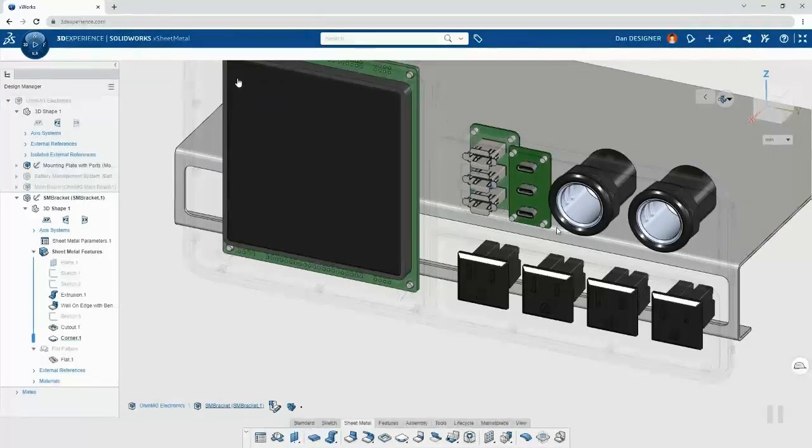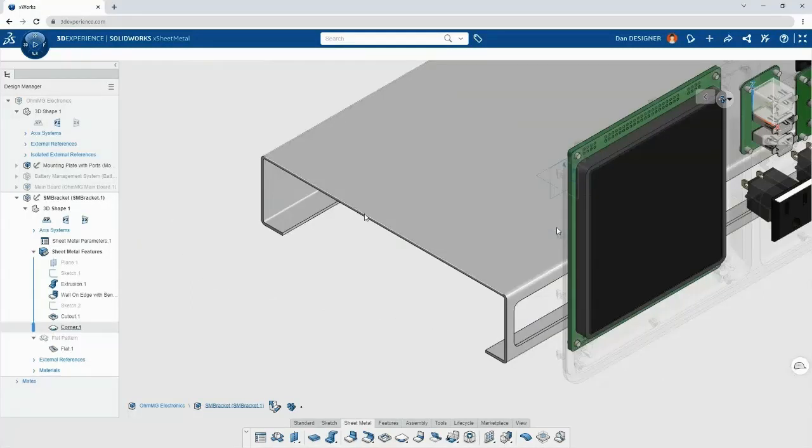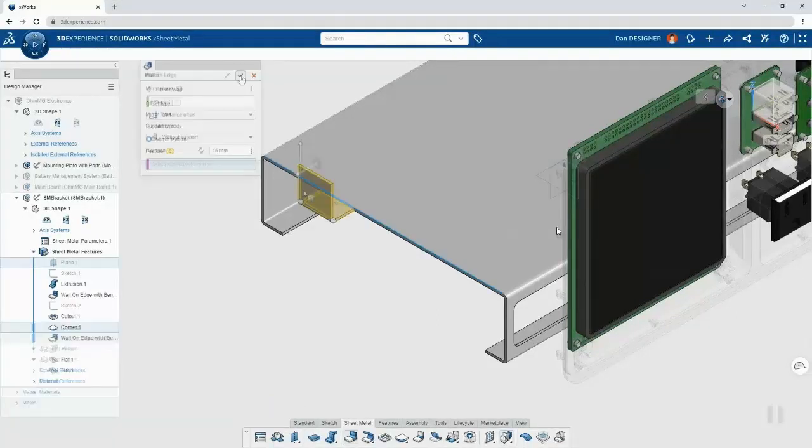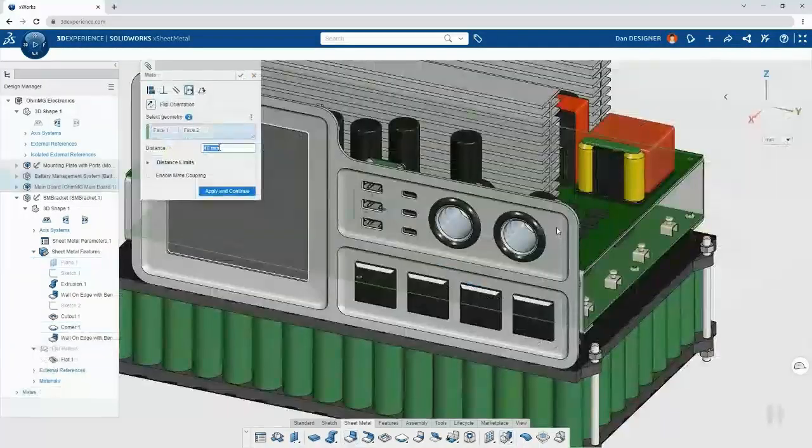Some corner treatments. Okay, simple corner treatments, typical sheet metal commands. The thing about X sheet metal is it's purpose built for sheet metal. So you'll see a lot of the terminology like cutout. We're used to calling cut extrude, right? A cutout in a sheet metal makes more sense. So some of the terminology will be purpose built for a sheet metal tool.